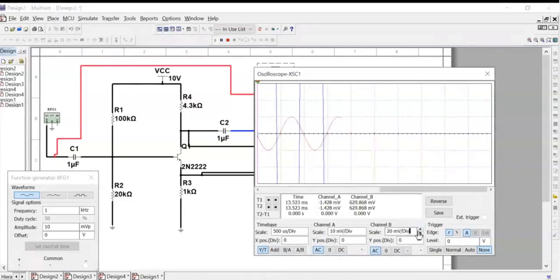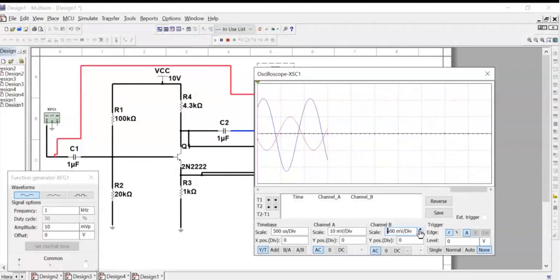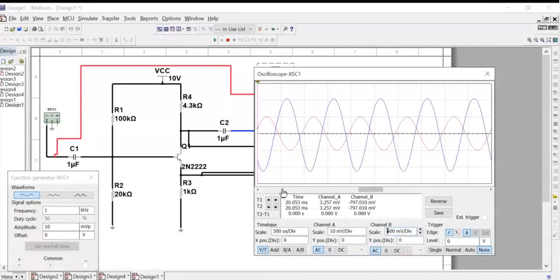So meaning we need to increase the volts per division. This will be the new output. It is higher than the previous measurement. So get again a screenshot for this one. This is with bypass capacitor C3. So with bypass capacitor C3, this will be the waveform.